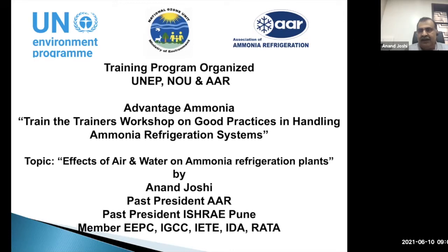See, ammonia is mostly a site-built refrigeration system. Other than chiller packages, most of the things are built on site. So they are designed as per the customer requirement. It's not normally that you buy a 5 TR, 10 TR, or 15 TR package and combine it into the system.